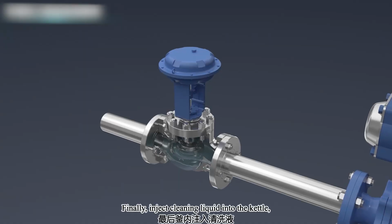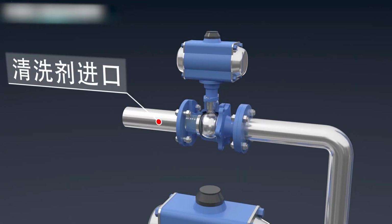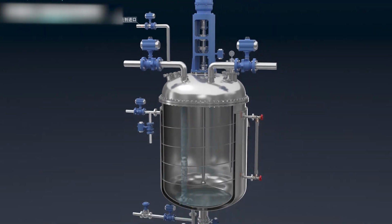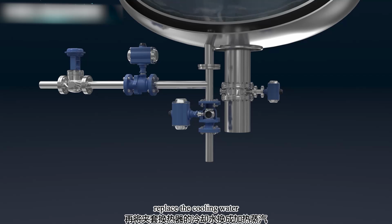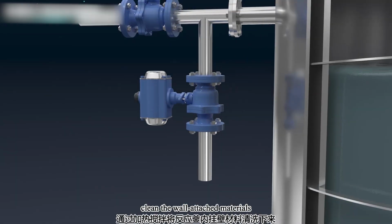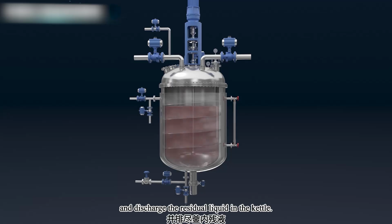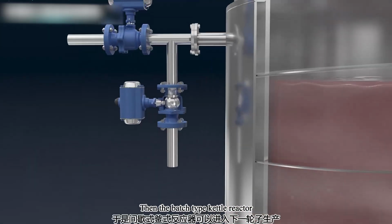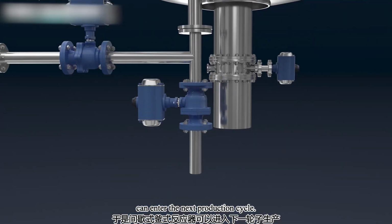Finally, inject cleaning liquid into the kettle. Replace the cooling water in the jacket heat exchanger with heating steam. Clean the wall-attached materials in the reactor by heating and stirring, and discharge the residual liquid in the kettle. Then, the batch-type kettle reactor can enter the next production cycle.